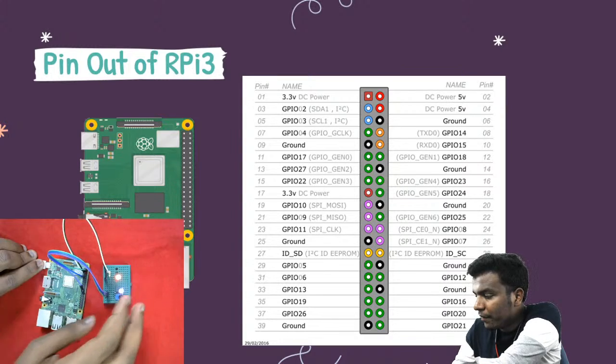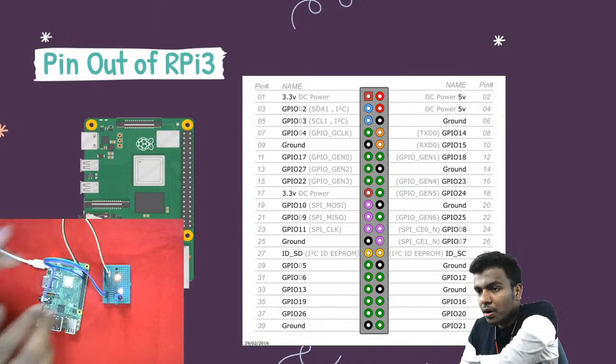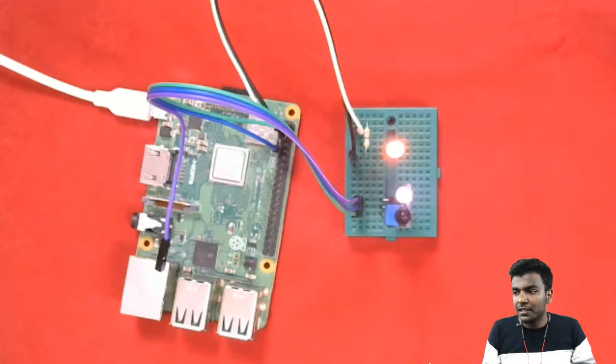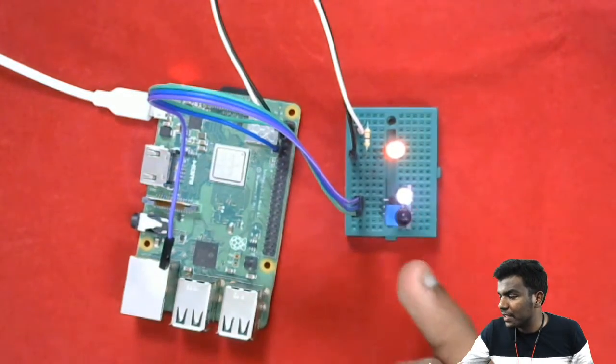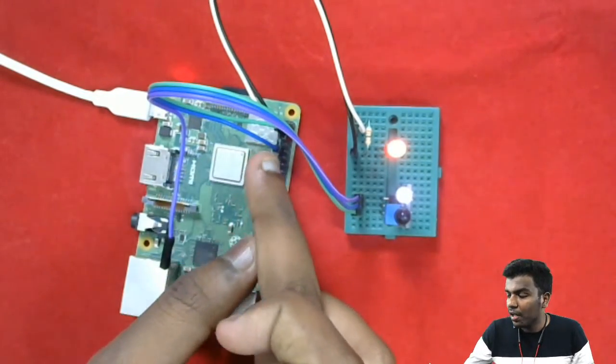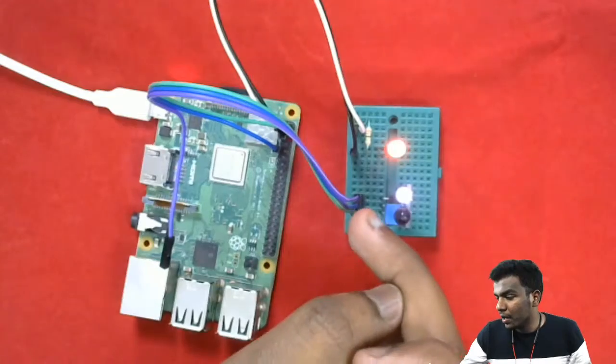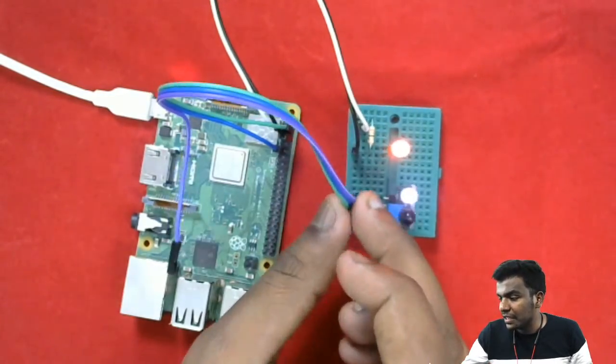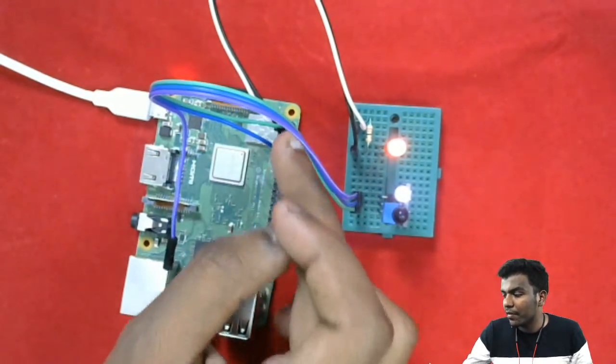Okay, so now we have given two wires. One is VCC and another one is ground. On the IR sensor, one pin is ground, so ground is given to the left side, fifth pin, and then VCC is the right side second pin. So we have given that.